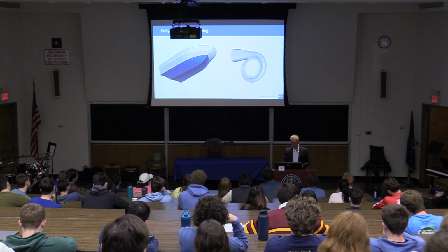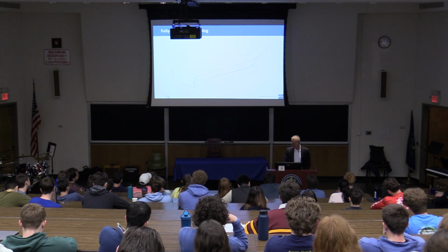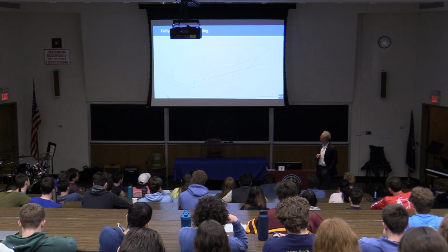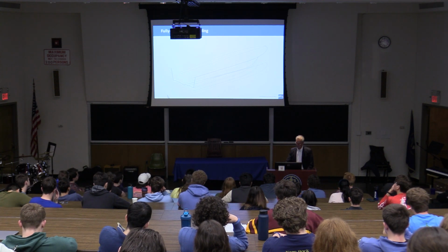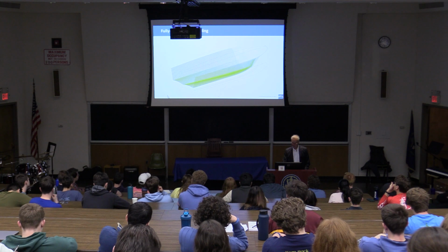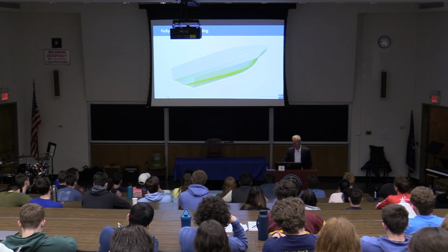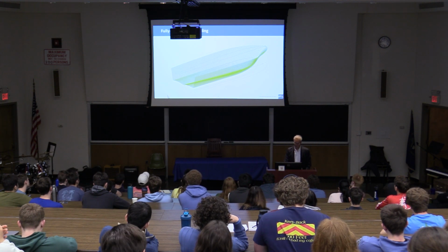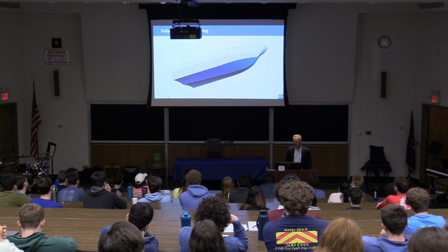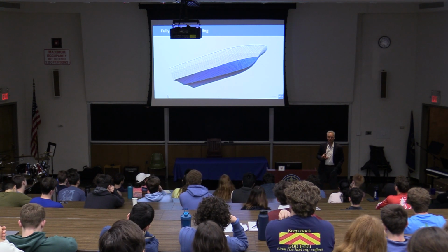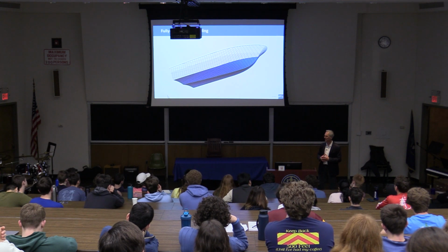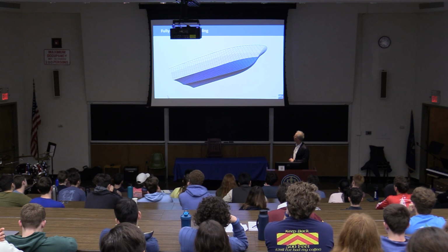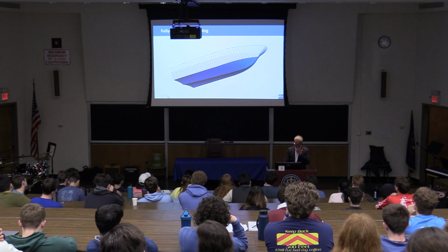Okay, fully parametric modeling. You can use fully parametric modeling very nicely to make really complicated shapes with very few free variables. And I'll show you along that line of the fast monohull that we have seen at the start, we basically just lay out curves in one direction, typically a longitudinal direction for a hull, and from which we can produce what is called a metasurface. A metasurface is a specific type of surface that readily uses all the input from a pattern and from those longitudinal curves to build the surfaces. Okay, now we have a fully parametric model.